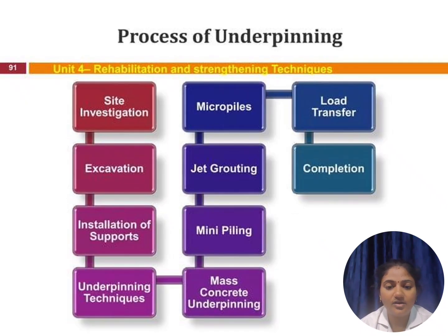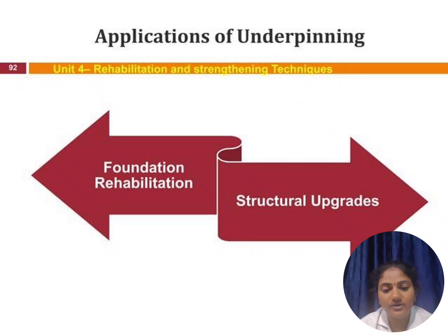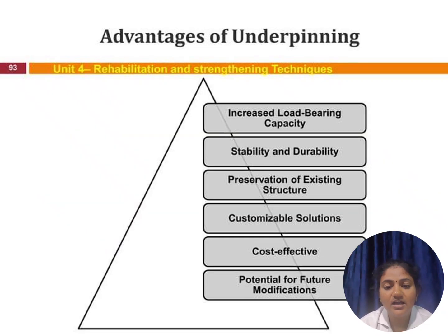The process of underpinning first goes with site investigation, and then excavation is done. After excavation, supports and underpinning techniques are installed. We have some proper techniques to use: mass concrete underpinning, mini piling, jet grouting, micropiles, and then load transfer and completion. Applications are foundation rehabilitation and structural upgrades. The advantages of underpinning are increased load bearing capacity, stability and durability, customizable solutions, and potential for future modifications.